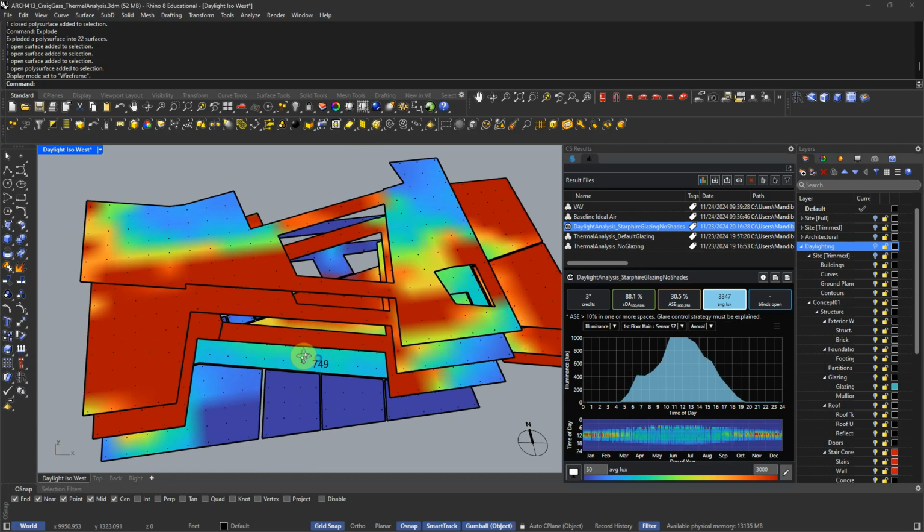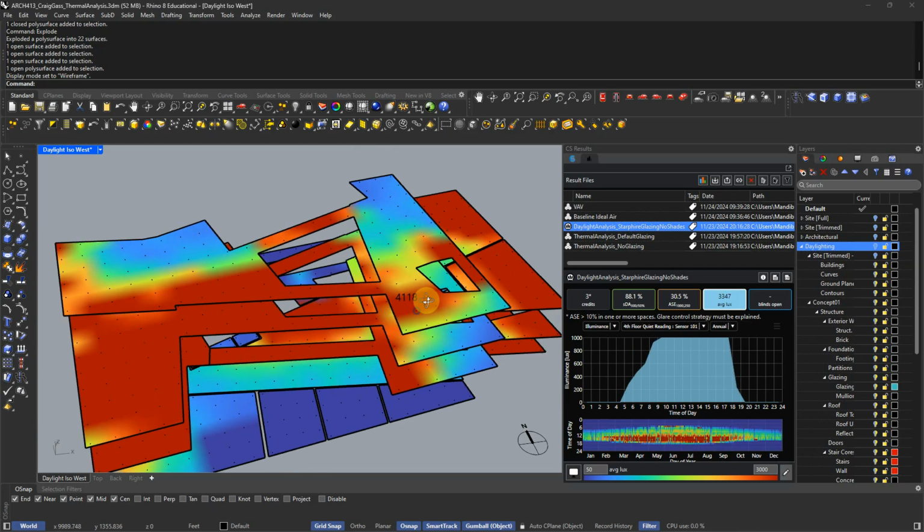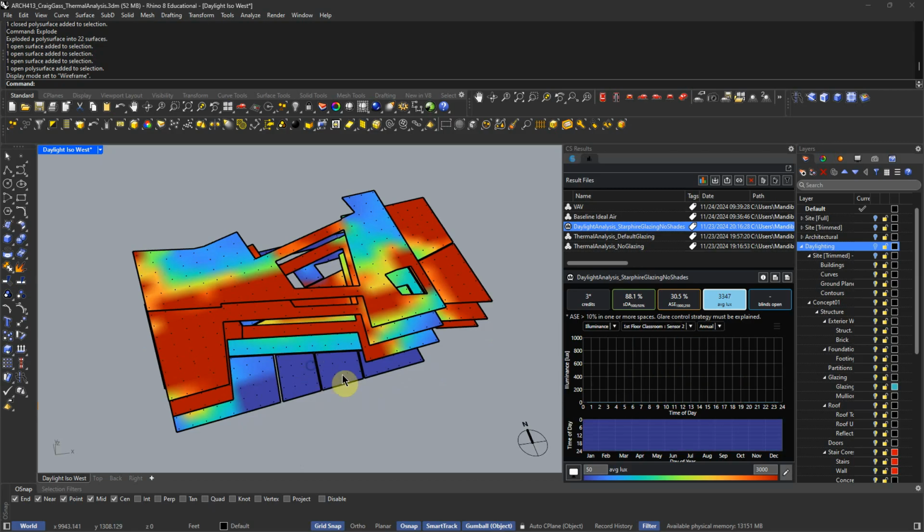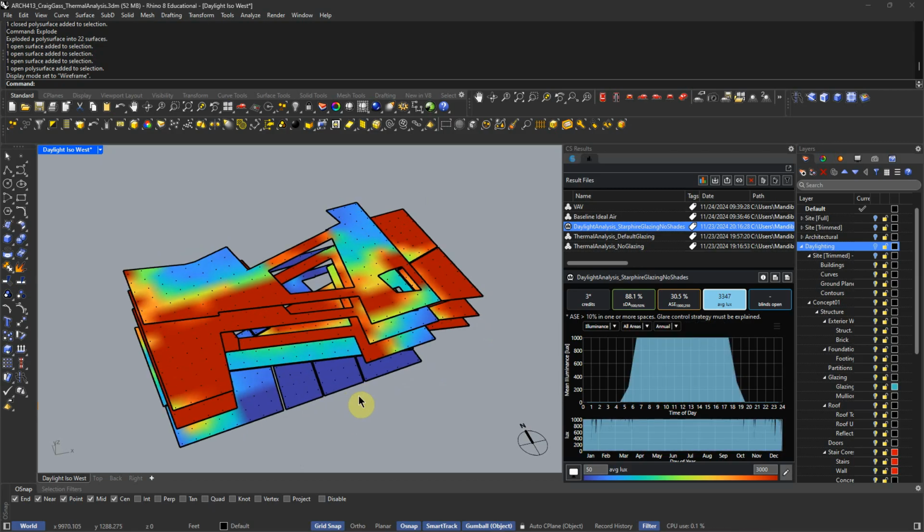So the first thing you would need to do here is break these work surfaces up into subsets so that we can take out those areas. We can only be simulating the regularly occupied hours. We also need all the partitions. I think you know this already. The partitions would have a material on them, and then they're going to be reflecting and blocking the sun.